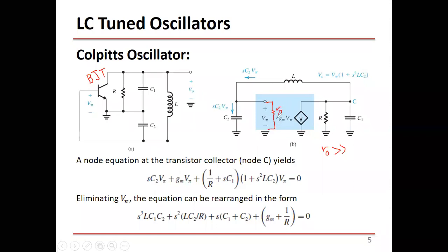So this is R pi. And again, we assume that R pi is very, very large, so we assume it's infinity. In this analysis, just for the sake of simplicity, we're going to assume both R naught and R pi are infinity, so we are not going to use them. Okay, so let's analyze this one. We need to do KCL at this node here.